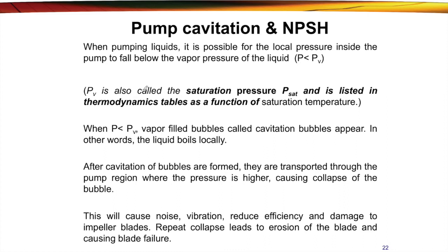These bubbles fill up the pump, and when they approach the wall of the pump, they will collapse. This collapse will make the pump vibrate, and when the pump vibrates, it causes noise. The continuous formation of bubbles will damage the impeller blades. So we want to avoid that kind of situation.